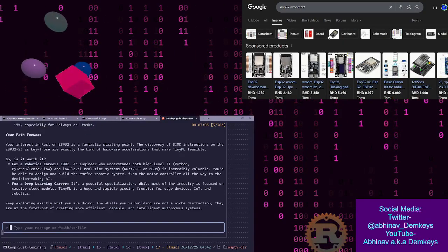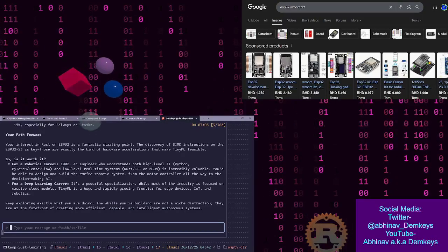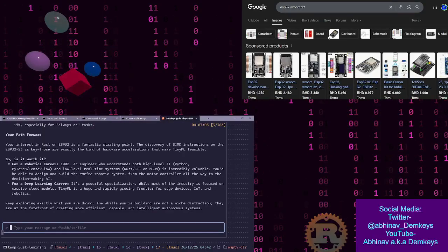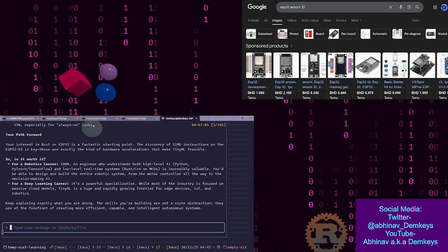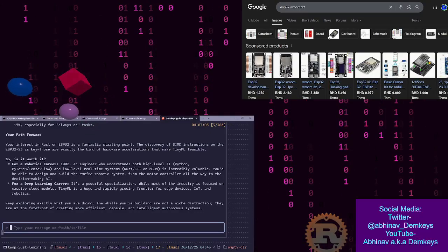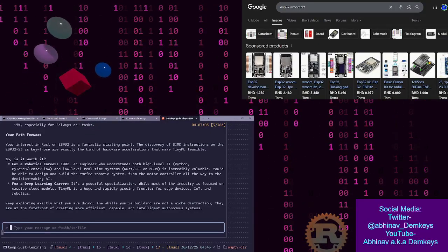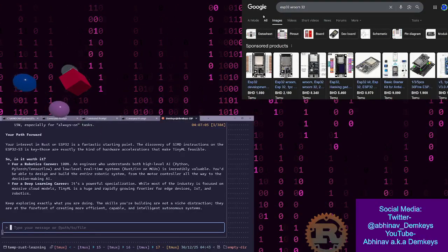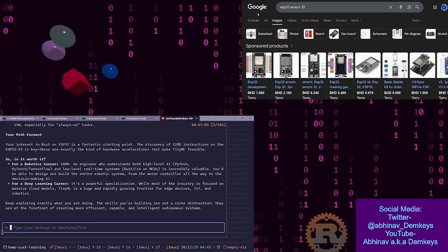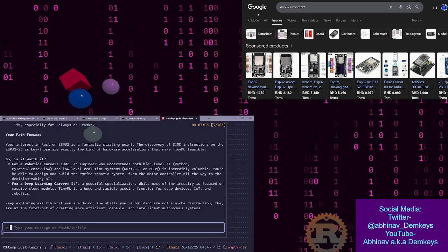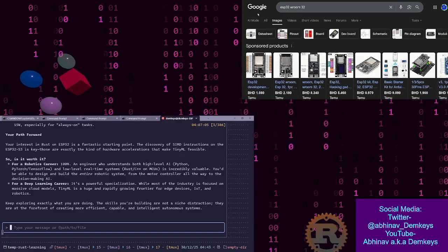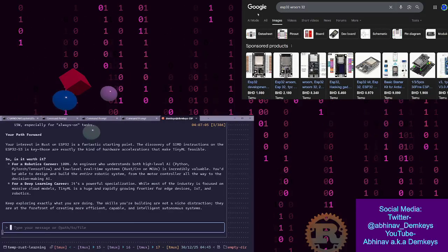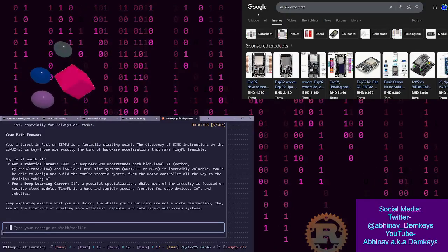That's a fantastic collection of boards. Rust and the ESP32 are a powerful combination, though the learning curve for embedded Rust can be a bit steep because you're managing hardware at a very low level. The good news is that almost all ESP32 variants, including the C3 and the classic Vroom, have a built-in internal temperature sensor. Measuring temperature in Rust: the internal sensors measure the die temperature, that is the temperature of the silicon chip itself, not the room temperature. This is exactly what you need to see if the MCU is overheating.